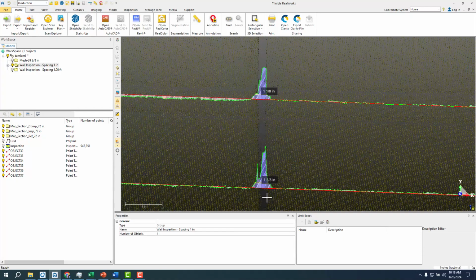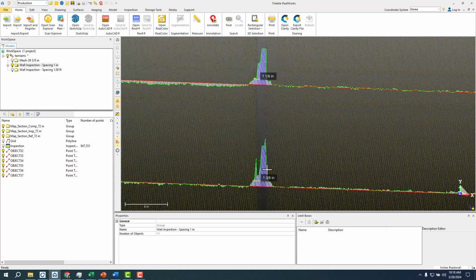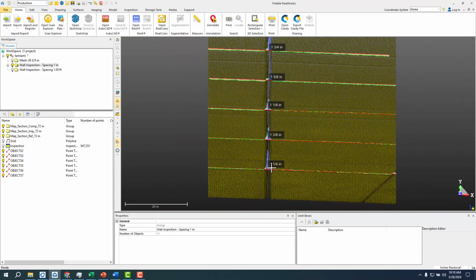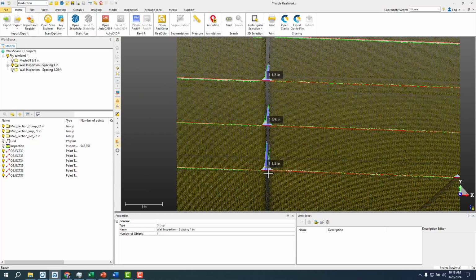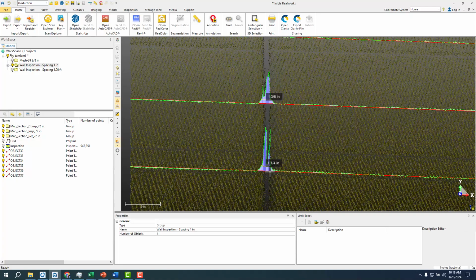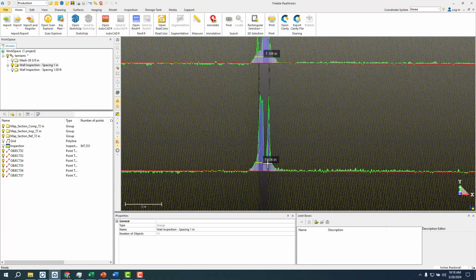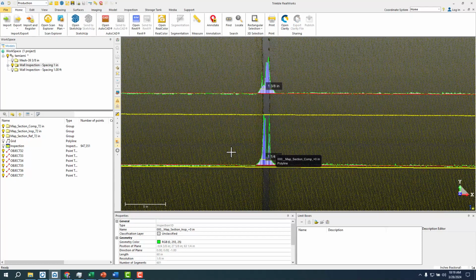And these blue lines are actually representing the segment or interval I selected, which is about 6 feet. The distance, so you can see the chamfer and then the actual distance between those two. I can export those out along with those measurements that you see here as 1 inch, 1 3/8 inch as a DWG.